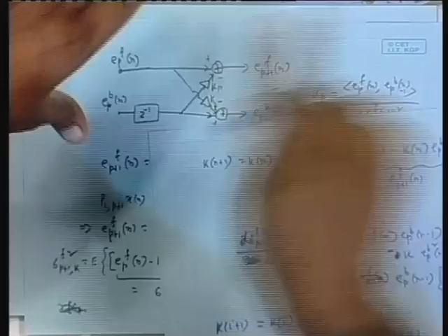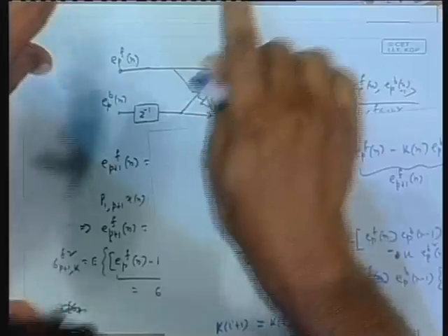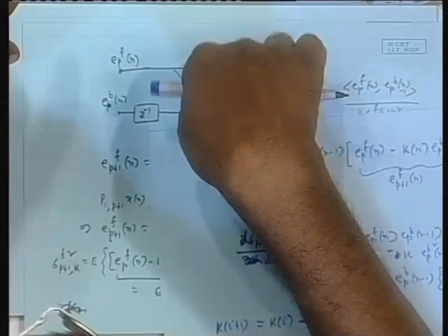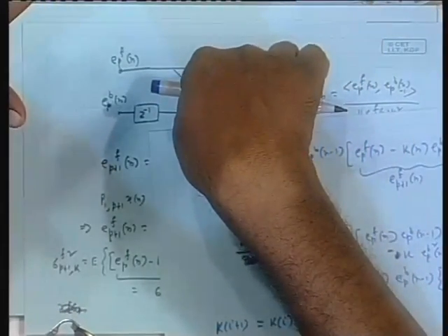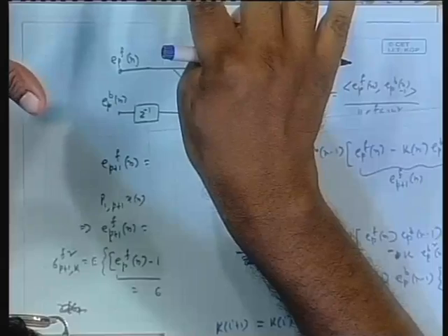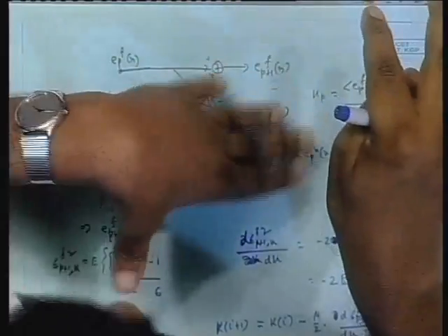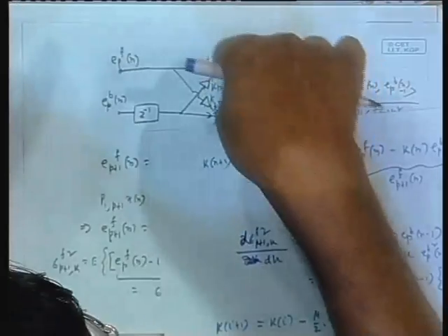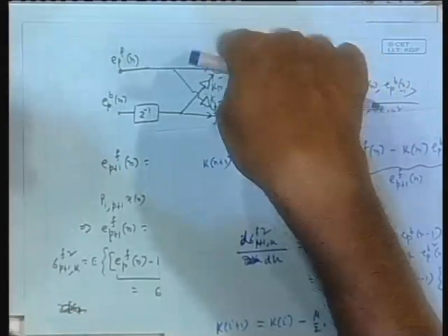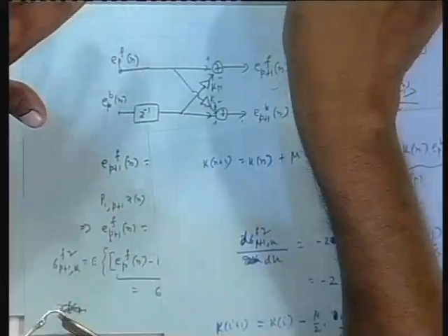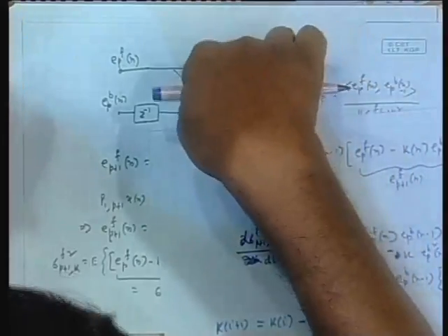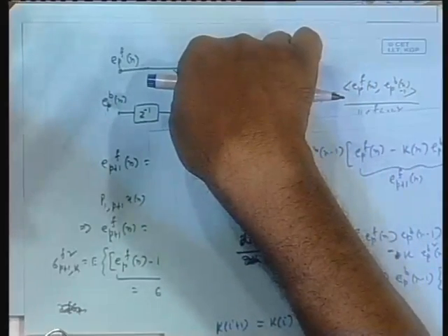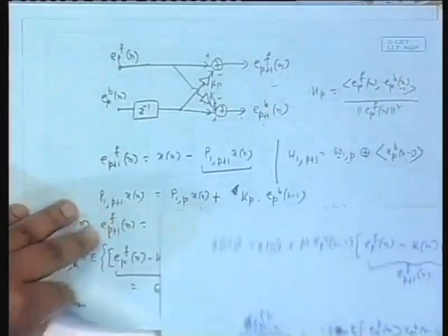In the lattice filter I have proved that these two must be the same in the real case. So that is never assured, isn't it? So I have to generalize this business somewhat, so that it is guaranteed that after convergence, even if it is only in mean and not exactly on the optimal Kp, these two fellows are locked to each other. To do that, it is very simple to generalize this.